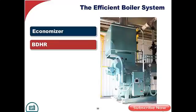Blowdown heat recovery I mentioned. What about an economizer on the stack? It could be a condensing economizer. It could be a standard economizer. If I've got a lot of hot water need, where I can take 55-degree water and take it through the secondary exchanger and an economizer and bring that water to a tank for whatever potable use might be considered, I can save boatloads of bucks here.